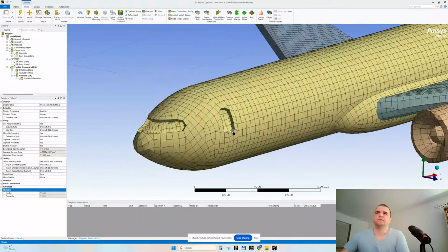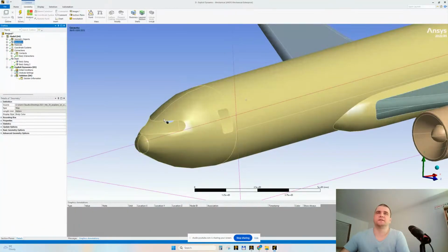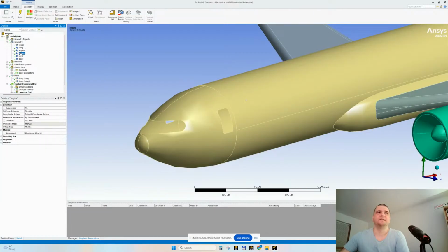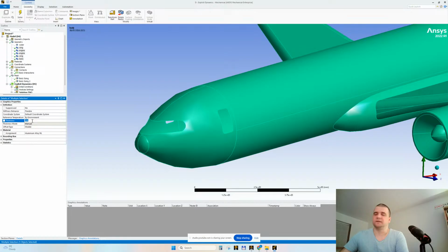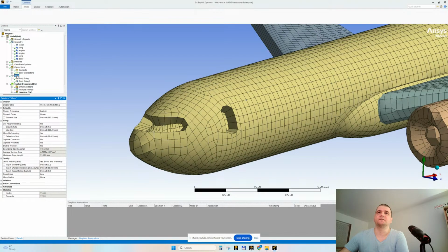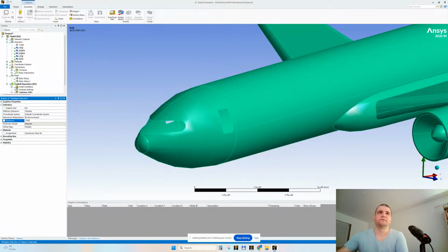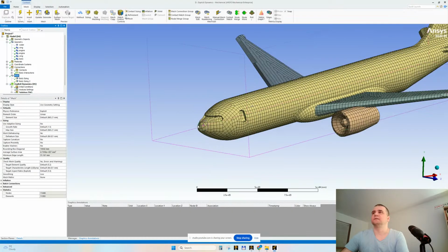So now do you see the thickness? The thickness does not exist in the geometry model, but when we meshed, then the thickness appears and is visible because we have assigned this thickness here. For example, if I change this thickness to 300, or no, 500, let's say, you'll see how much it increases. Yeah, you see? This is 500. If we make it again 150, then you can see it like this. All right.